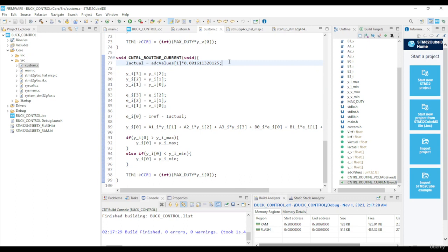But obviously when you're going up in the current, when you have to sense high current values, like I'm talking 15 amps and above, it's not advisable to use a shunt. The shunt changes color and things like that, and changes resistance at some point, and it affects the efficiency of your converter.